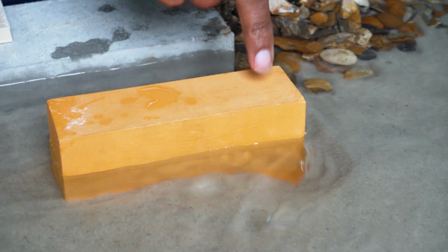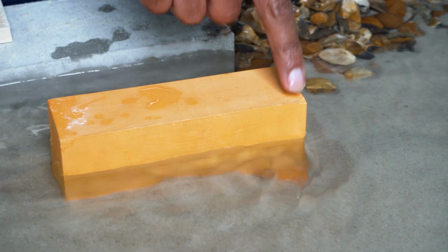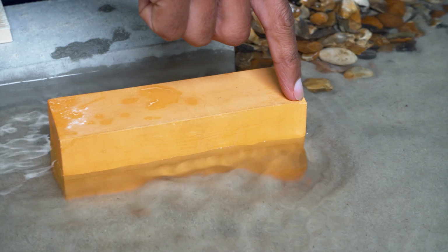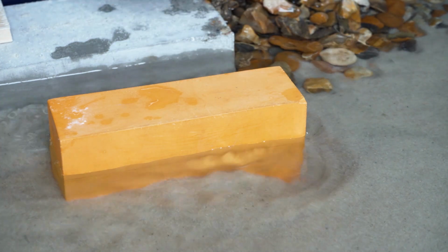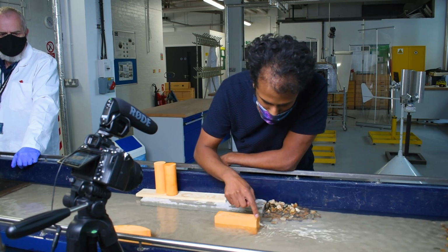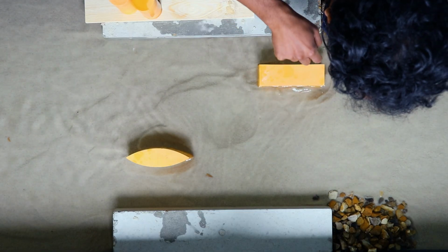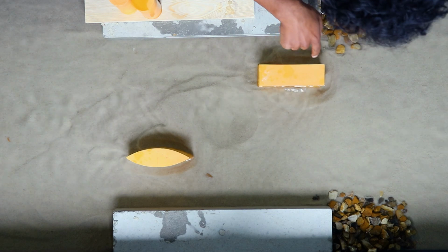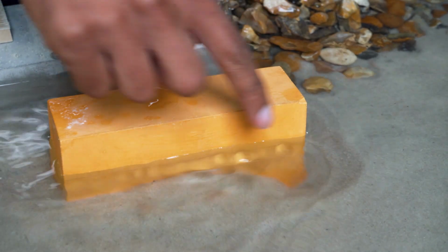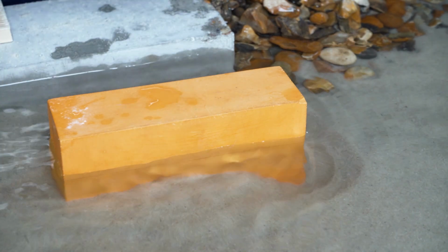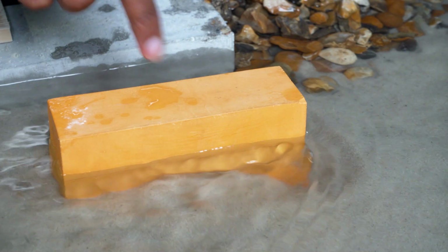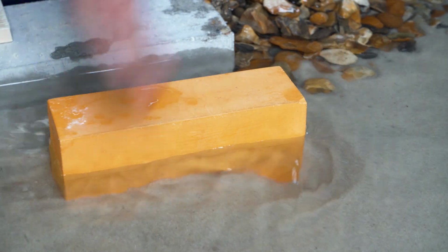Ignore that one. Back to this square one, you can see the flow's approaching, and then it comes to the leading edge, the leading corner, and the boundary layer will separate because it's such a sharp corner it can't stay attached. And so as it separates, you can see there's a swirling of sediment along the corners. When you look very close, you can see that a lateral vortex has formed. It's taking the sediment downstream, but at this point it loses a lot of that energy, and so the sediment comes out of suspension, and we get quite a lot of deposition on this side towards the rear of the structure.